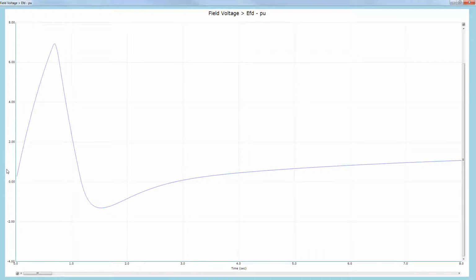And during a specified amount of time, which could usually be 30, 40, or 50 seconds, we allow the exciter to reach its internal states and finally reach the desired steady state operational value. This process is what we call internal initialization, and it is something that we can observe graphically in this image, and it's something that occurs in the background in the test routines that we have built into the program.